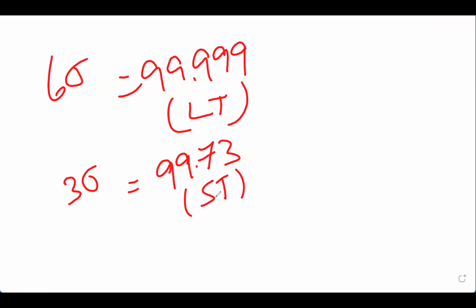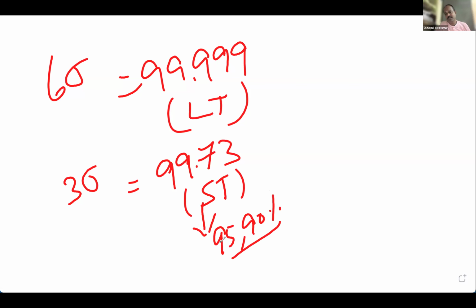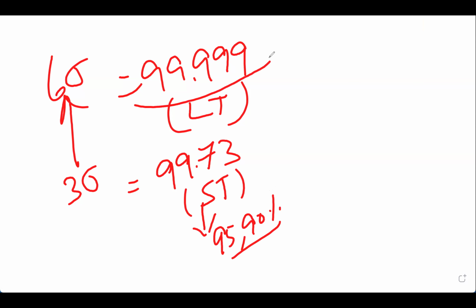Normally, people can easily deviate from the plan. So 99.73 can drop to 95 or can drop to 90, and that will be the actual success experienced by many companies. So there is a compelling reason to elevate the capability of the process higher than the 3 sigma capability. And if you bring it to 6 sigma capability, imagine your success rate. Failure has become almost a rare event.